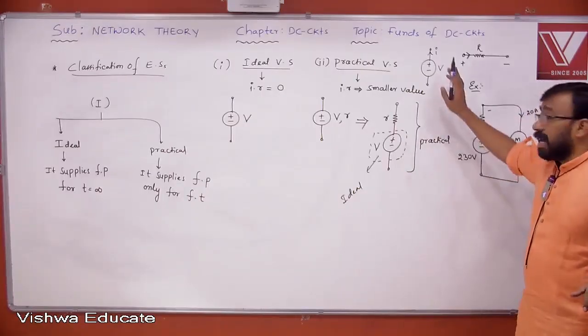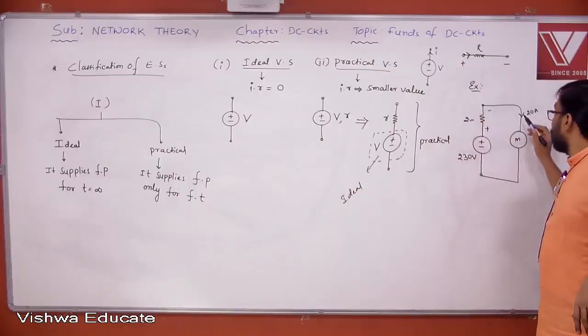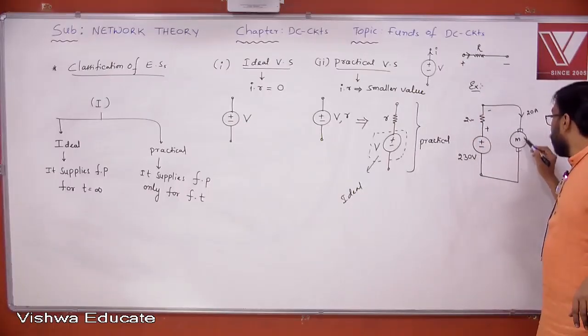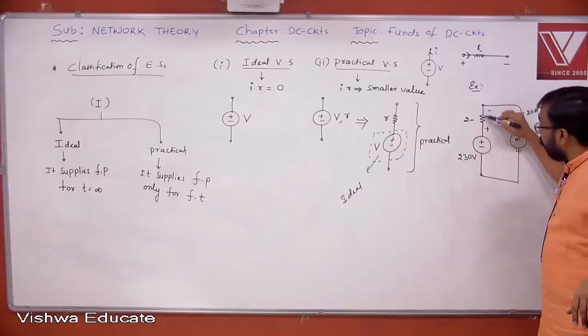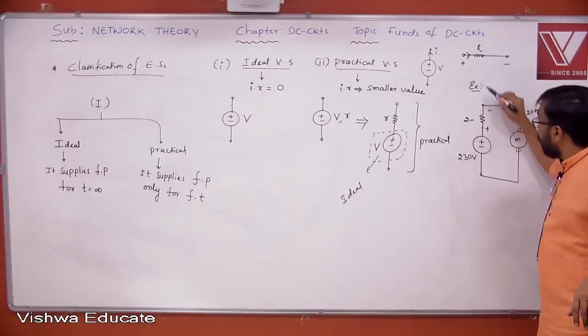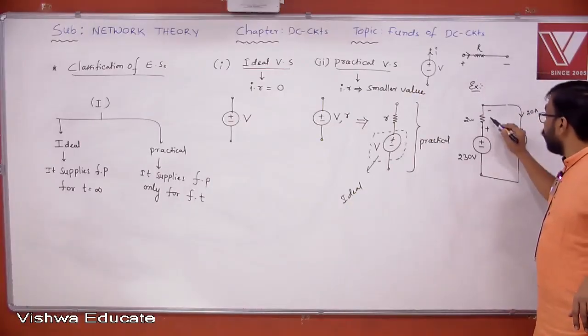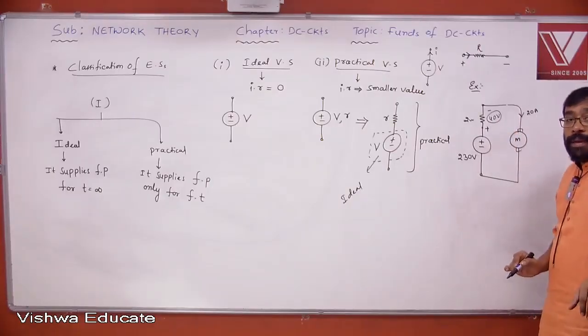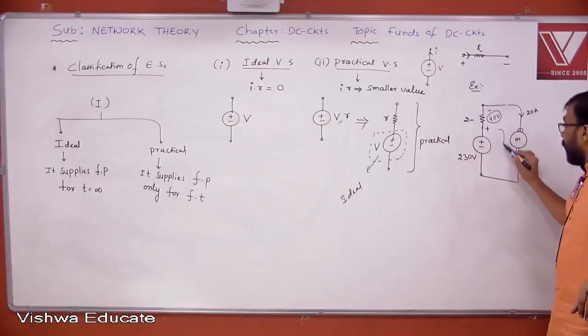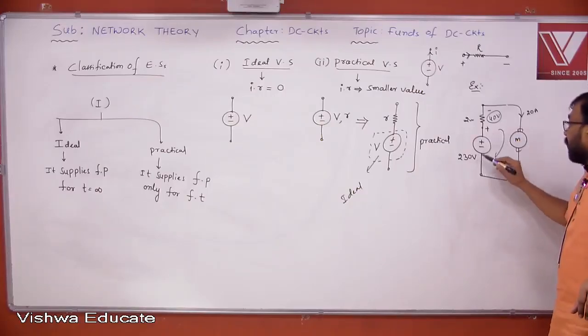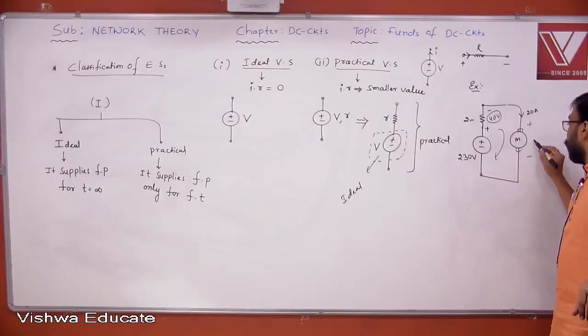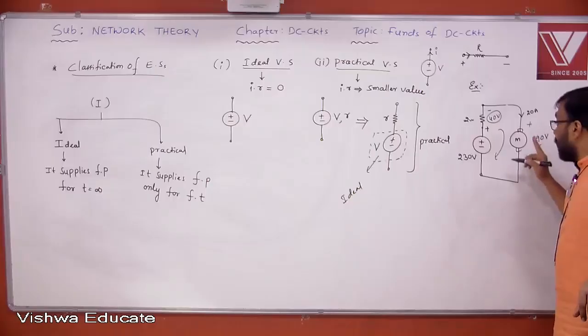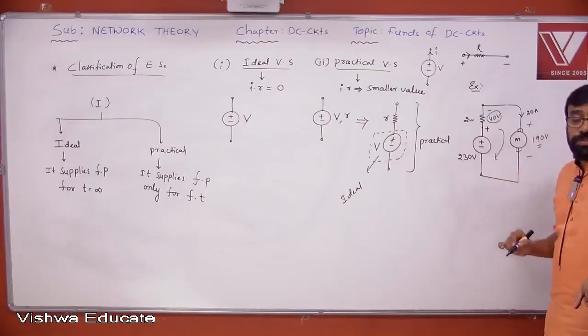Okay. We'll come back to this once again, but look at this. What is the direction of current? Actually, the motor is drawing here. Therefore, based on this direction of current upward, this is plus, this is minus, and 20 into 2, what is this value? 40 volt. Understand? Now, according to KVL, when you apply this is 230, then what could be the voltage here? 230 minus 40, what is this? 190 volts. That means the motor is experiencing the low voltage problem.